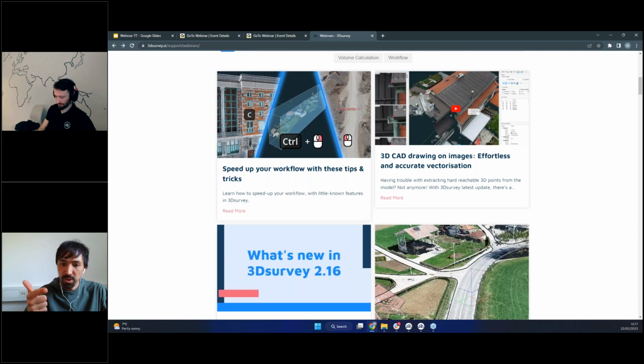The second important thing is what kind of coordinate system you actually selected. If the coordinate system is in US survey feet, it will actually write US survey feet. So please check the coordinate system. We will also check this one, because we had this issue 2 years ago and it should be solved.